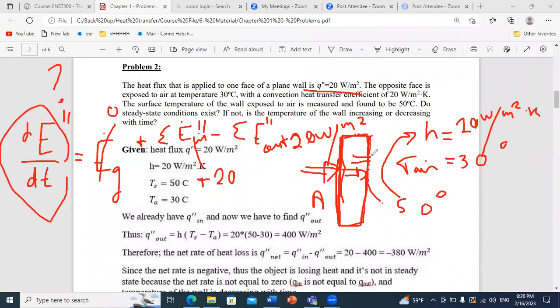But whenever you want to transfer to the outer environment, it will be by convection. Because you only have still air at the contact with the surface because of the no-slip condition that you know from fluids. And then because you have a fluid moving, it will transport this heat by convection. This is why we say that the wall will lose heat by convection.